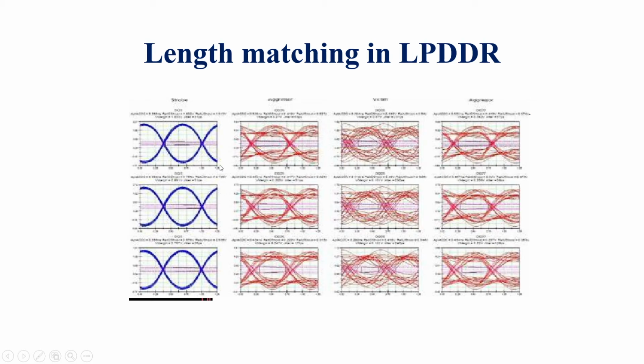The more eye opening is required. The more eye opening represents the signals are transmitted properly to the destination. If the eye opening is very narrow, then it represents the signal is not reaching the destination in a proper manner. For that, sufficient terminations are provided to control the signals to travel to the destination with greater eye opening.